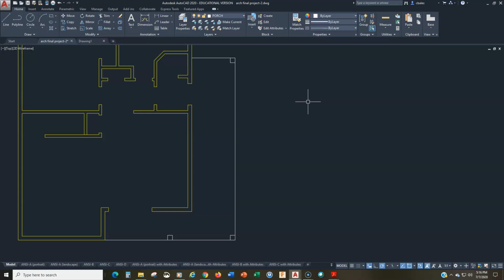This is kind of the curious thing with the divide command. What it did was add what are called nodes or points at the point where the sections are divided. We can't normally see those because they're in the middle of the line. So watch, I'm going to go to the move command, and I'm going to window this whole area right there. Clearly I'm not going to get the line there, the edge of the porch, because I'm not getting the whole porch in there.